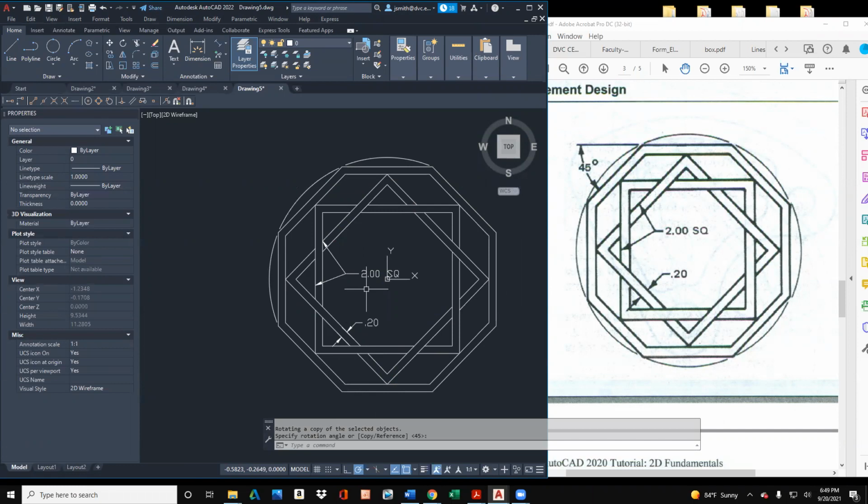All right, let's do it one more time. So 1, 2, 3. I'll push enter, select the object to rotate, and you get the idea here. Copy. All right, and then let's try doing it again. So push enter, select objects. Let's see if we can do this in one fell swoop. Base point 0, 0, enter. Rotation angle 180. Let's see if it works. Oh, I forgot to push copy. Silly me. Let's do it again.